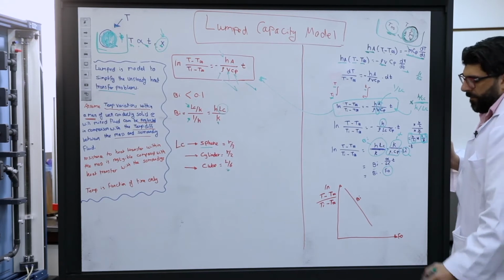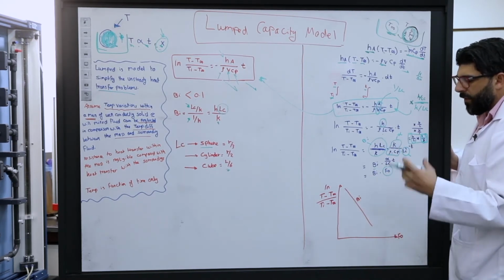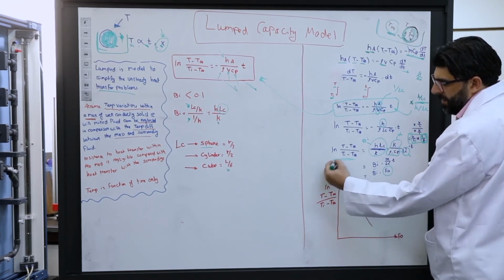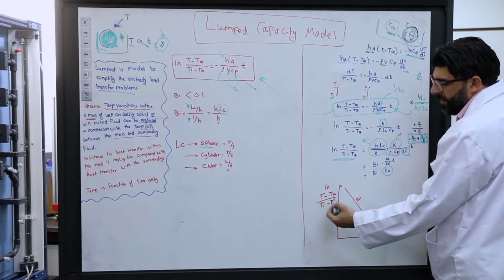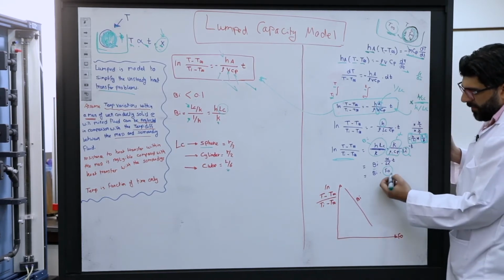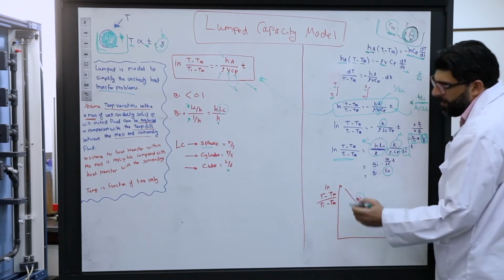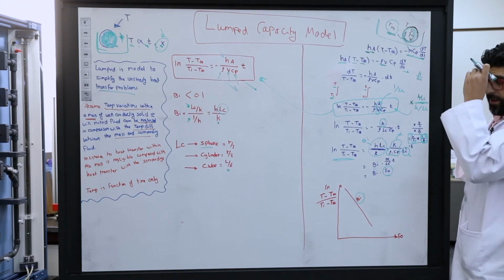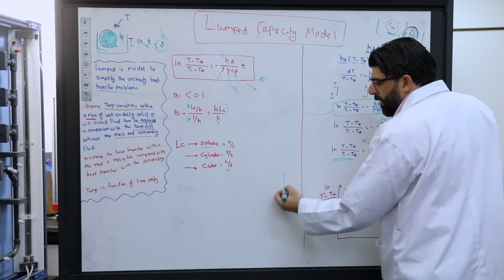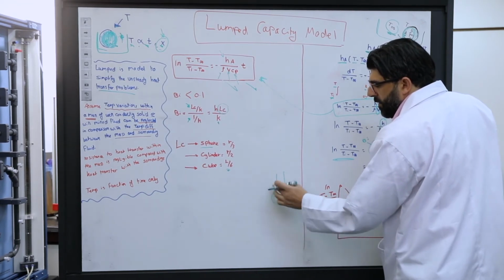Now, we can say this is the overall unsteady heat transfer. So on the left side, ln of (T minus T infinity) over (T initial minus T infinity) against the Fourier number, we should get a slope equal to the Biot number. So in the experiment, we have a shape, any shape, but in our experiment, our shape will be a sphere.